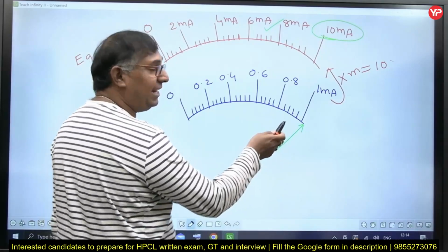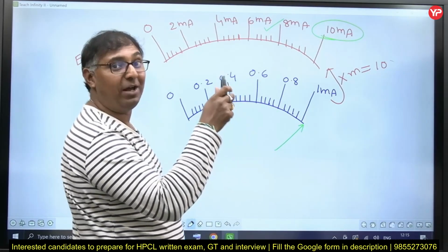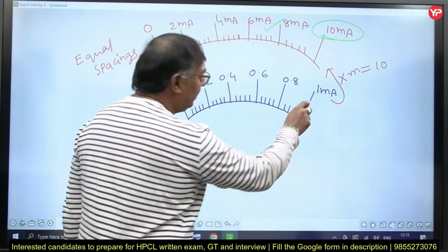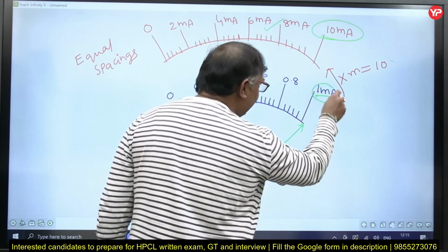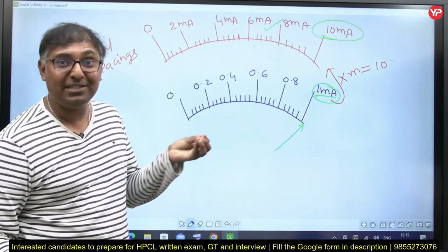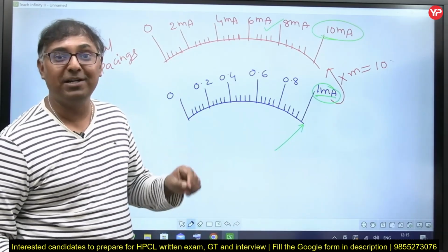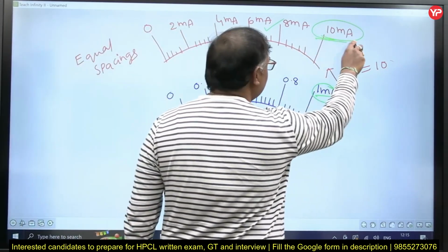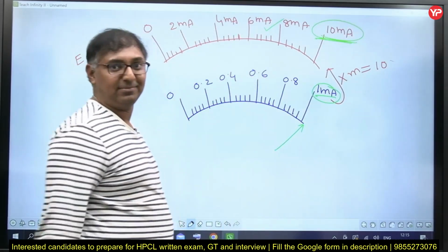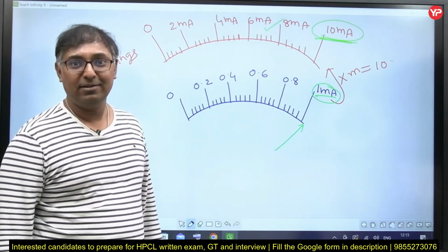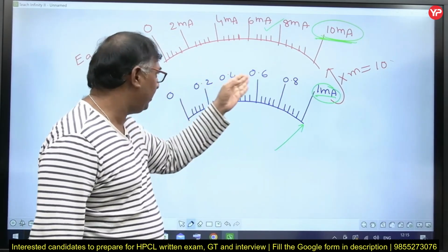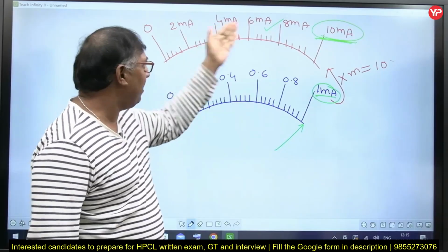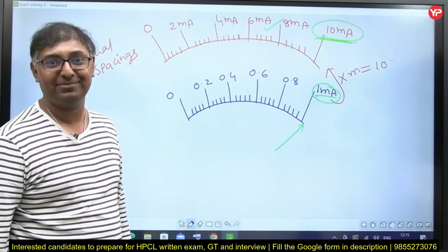So now what's happening, sir? When you're sending 10 milliamperes, 1 milliampere is flowing to the meter, and that is indicated as 1 milliampere. For 1 milliampere the indication is this, but in place of this 1 milliampere, now what is printed, sir? 10 milliamperes is printed. The manufacturer will erase these points here, 0, 0.2, and print new values and give it to the customer.